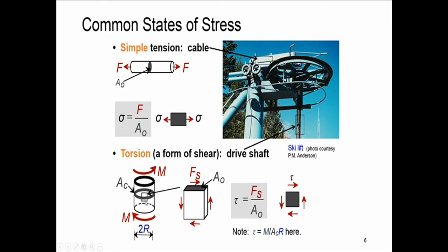If we look at a small chunk, a cube of this part, then we can see shear forces acting in this direction due to the load, the moment at this part, and the other moment at the other side of the cube. And we will have these moments in order to remain in the static situation, so that we have these acting forces on the cube.